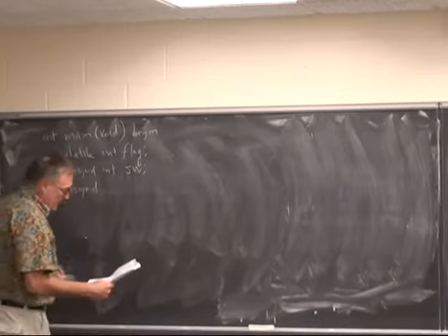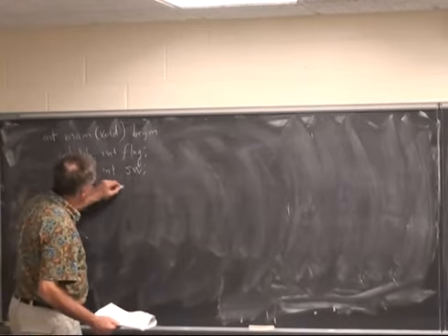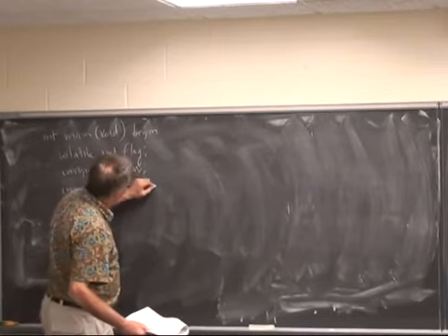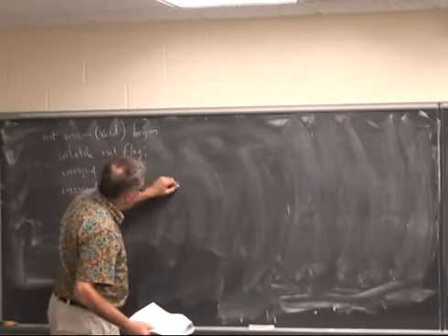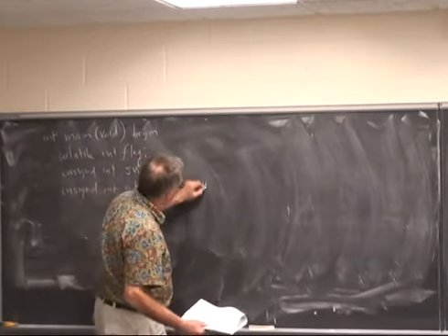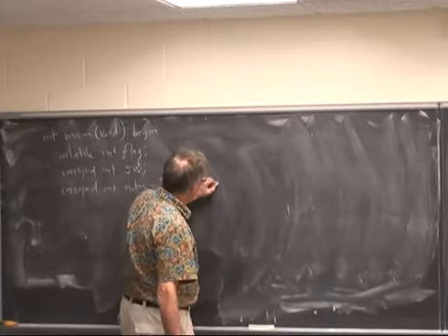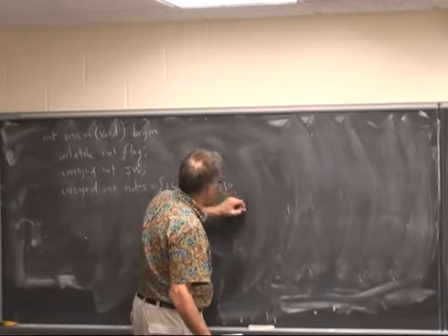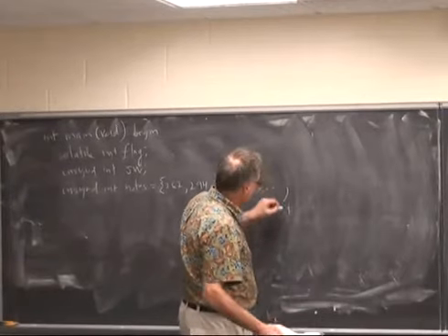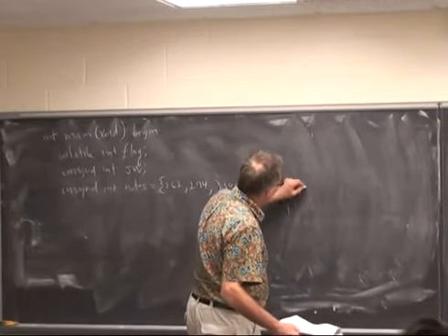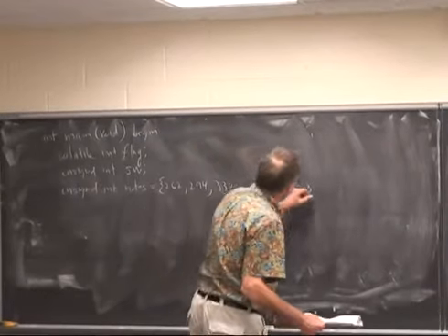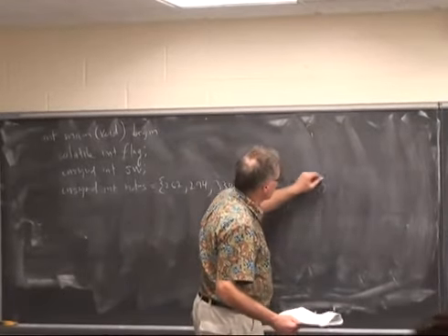And then we need an unsigned int array of notes, which are going to have the values 262, 294, 330, and so on, up to 523, and then 0.